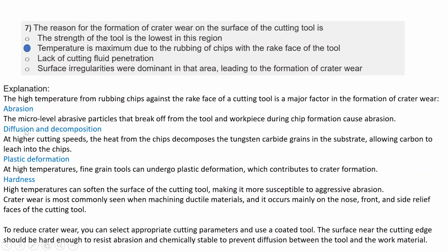First is abrasion, where micro level abrasive particles break off from the tool and also from the workpiece during chip formation. These smaller chips have very high plastic deformation, leading to work hardening, which can damage the tool with very high hardness.